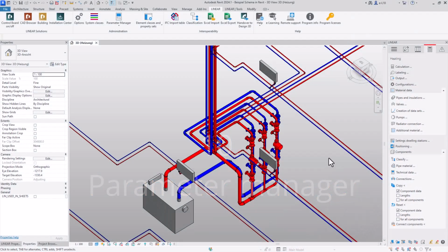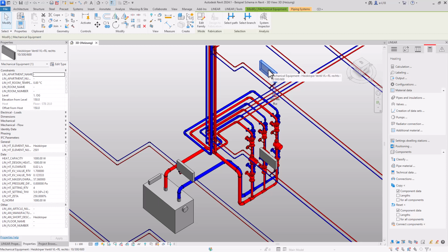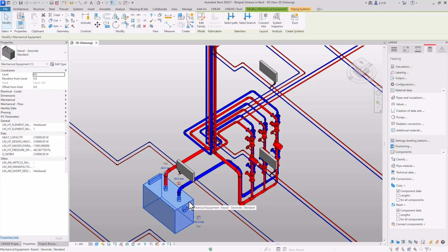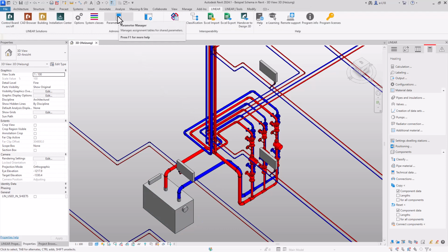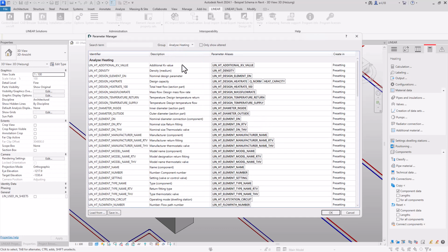The concept of shared parameters in Revit is the basis for consistent usability of all data in the model for a wide variety of applications. The fact that there are no uniform standards for all conceivable parameters makes it difficult to use them when projects or component families are delivered that were created with other tools or come from different sources. It can happen that component families for radiators are used in one and the same project, where the parameter for the heat capacity is called QNorm for one and heat_capacity for another.